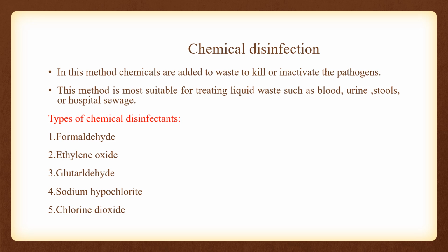So sodium hypochlorite may be widely used because of the relatively mild health hazards. And the fifth one is chlorine dioxide. It is a reddish yellow gas at ambient temperature. It also reacts with water or steam to produce corrosive fumes. It is an active agent against bacteria, viruses and spores.